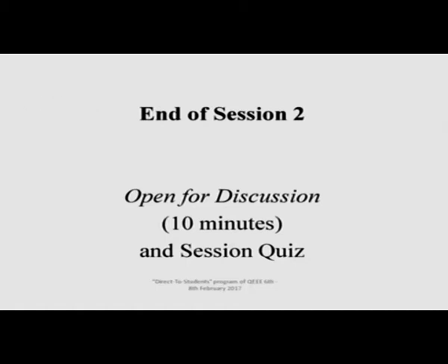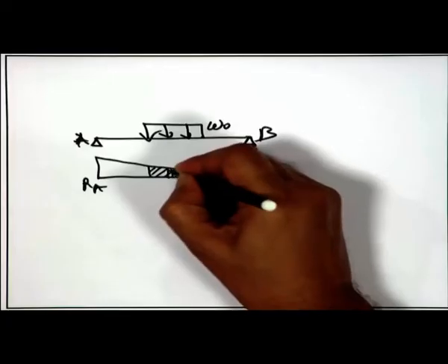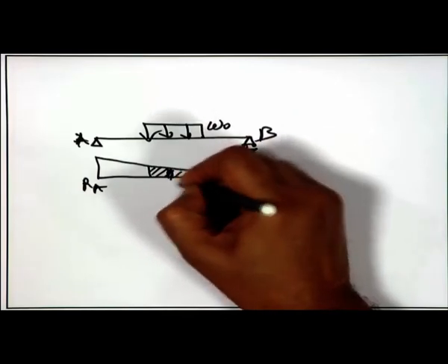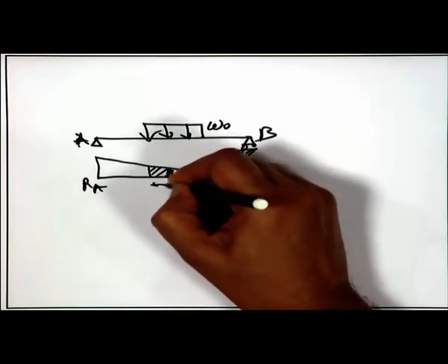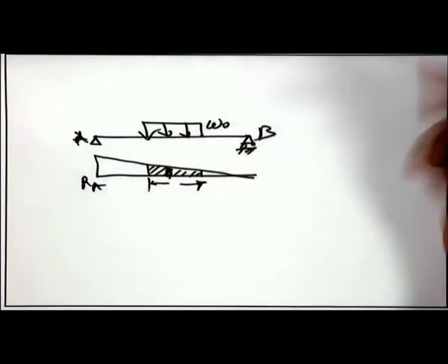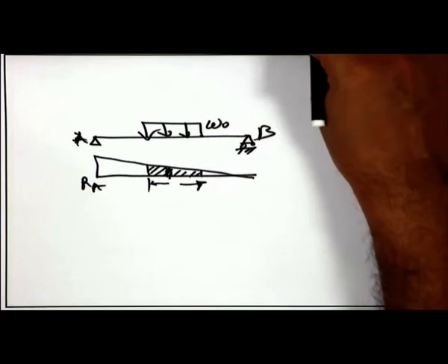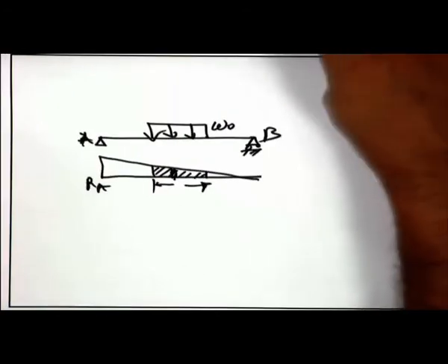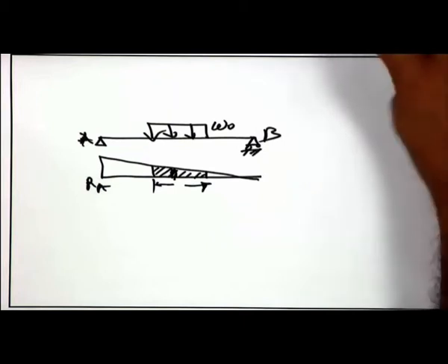Can you explain again how to calculate the area under the influence line diagram? Yes, the question is how can we find the area under the influence line diagram. It has nothing special to do with influence lines, it is the area under the curve. So, you use calculus or geometry, whatever you want. As I explained, you take your differential element, find out its area and extend it from one limit to the other. So, it is the limits of integration which define the area under the curve, or sometimes, if the figure is very regular and you are familiar with it from school geometry, you will find the area geometrically. It is very simple, try that.